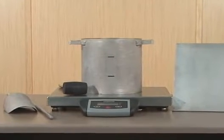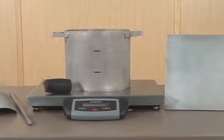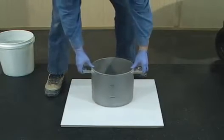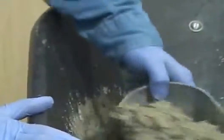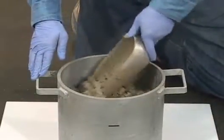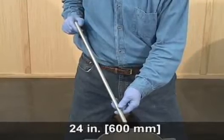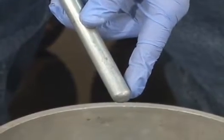The equipment needed for this test includes a measure, scoop, tamping rod, mallet, strike-off plate, and balance. Select an appropriate sized measure based on the nominal maximum size of the coarse aggregate. The scoop shall be sized to obtain representative material from the receptacle and not spill as concrete is placed in the measure. The tamping rod shall be a round, straight steel rod with a 5/8 inch diameter. It shall be approximately 24 inches in length, with the tamping end rounded to a hemispherical tip.